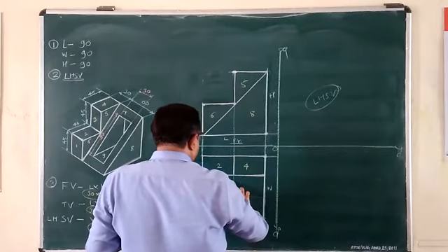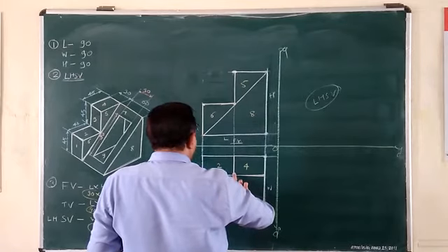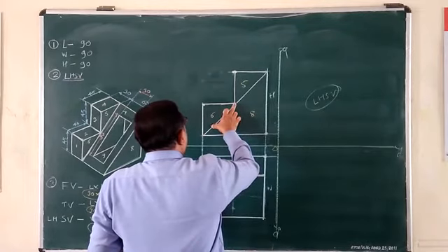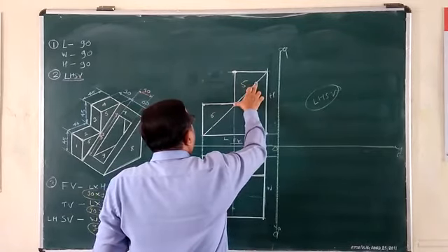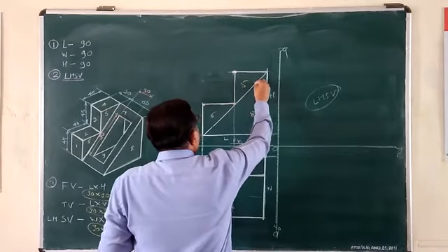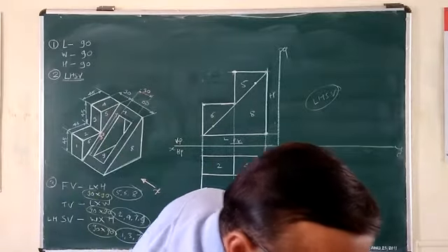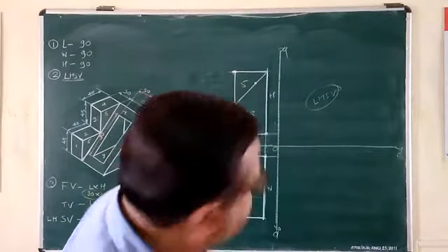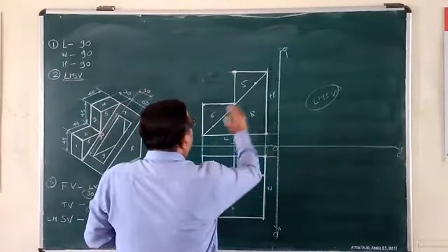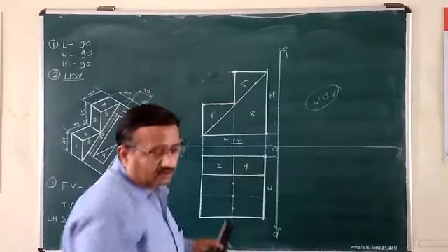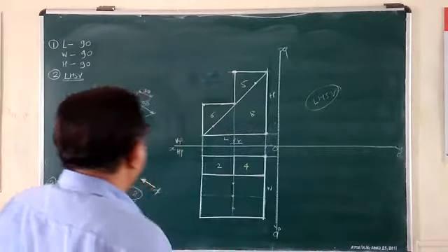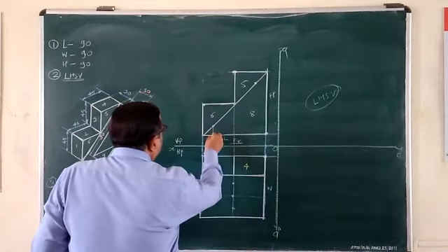Okay. So this is the 30 plus this much 45. So by scale only you have to mark. I am marking here approximately, but you should not do this activity approximately. You are having precise geometrical instruments. So use the scale. 45 left, 45 right, you mark here and get it down.